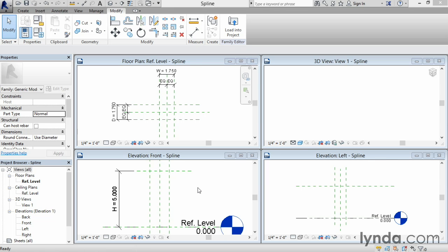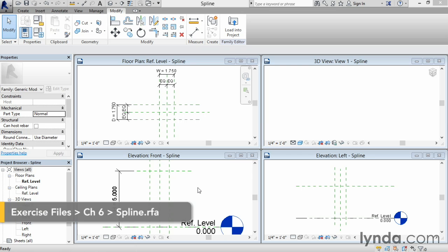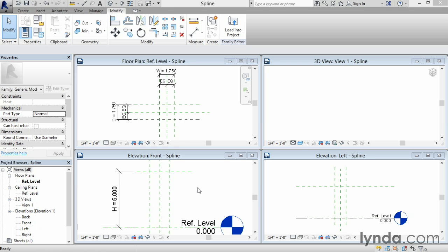I'm going to continue talking about proportional scaling in this movie, but show you yet another approach. In this case, it's a very specialized approach. We're going to leverage the built-in behavior of the spline object to help us control scaling of the forms that we generate from them. So I'm in a file called spline, and spline was generated from our GM seed file,